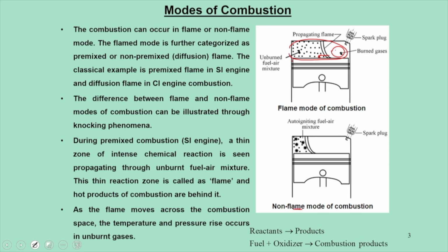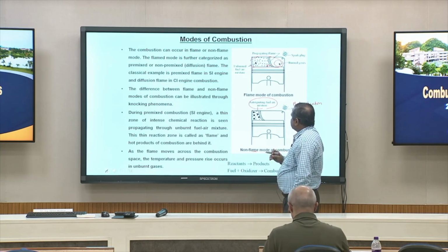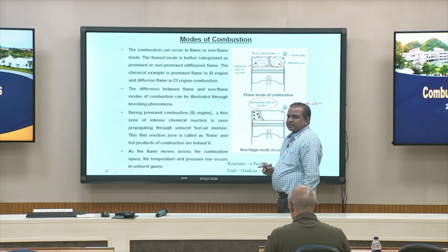In the other case, the non-flame mode, normally instead of a spark plug, we use a fuel injector, and there are possibilities that you can inject this fuel at various locations, and through this we can auto-ignite the charge. Auto-ignite means air and fuel come separately, and when the fuel sees high temperature and pressure air, it self-ignites. Although multiple flames open up simultaneously, we cannot create a specific flame that ignites the fresh charge.